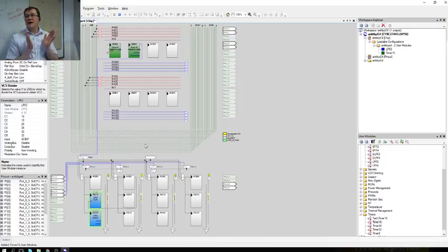So fundamentally that's all you need to do to make the low pass filter run. Plus, in the software, in order for that module to run, you must start it. But not only this module, you also need to start the timer module that gives the clock signal for that one. And not only those, but you need a programmable gain amplifier there. And yes, you have a question.